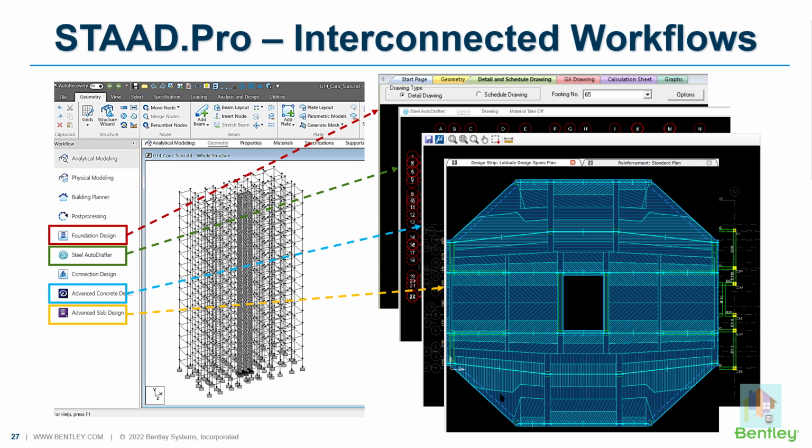So all these modules are interconnected with STAAD, and all these modules just use your STAAD.Pro geometry and the analysis results to perform the design. You don't have to once again create the geometry there or apply the loads. No, you don't need that. Rather, you just need to export the model to these modules. And all these modules come under the Structural Worksuite license. So if you have the Structural Worksuite license, you can use all these interconnected modules. Today I am not going to cover the other modules. I am going to cover only a single module, the Advanced Concrete Design module, or the RCDC mode.